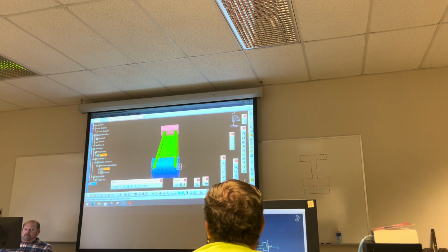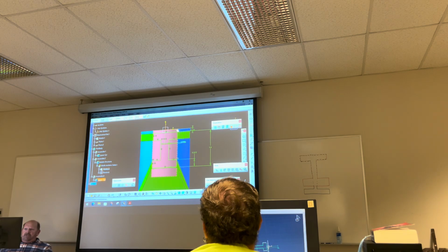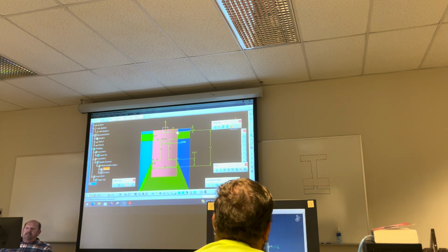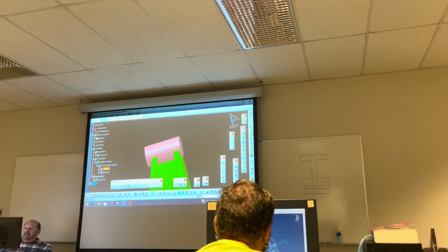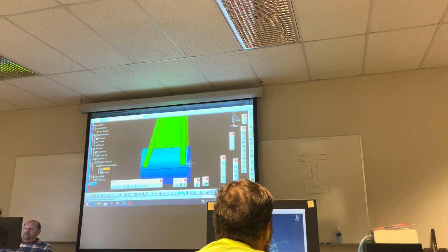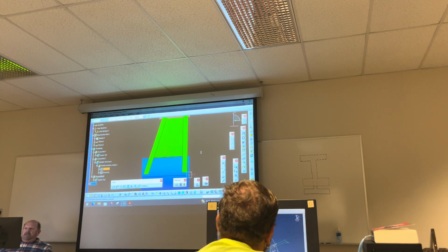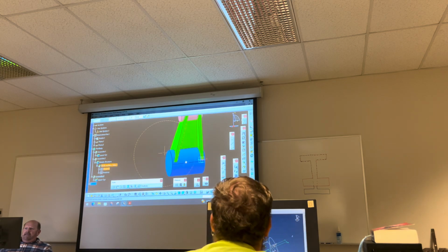What was that you just moved? Sketch 5, I had it 1/8 of an inch from the front and 1/8 of an inch from the rear. It was actually 1.5 from this to this. That's why it didn't look right when I exited the sketch. But it is definitely 1/8 from the front. This one, so in this view, these two, this is a planar line, or it's a vertical line, and in this one, it's an angular line.